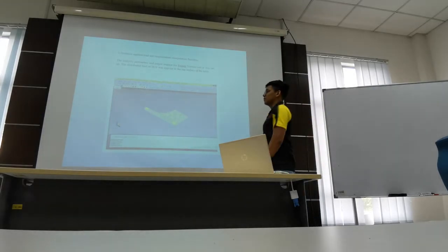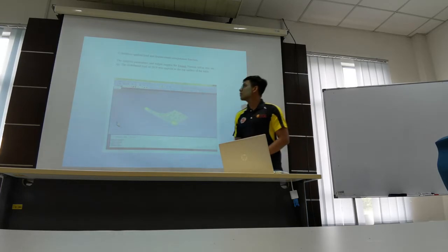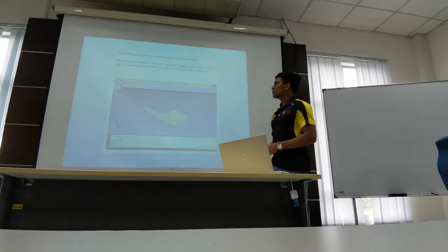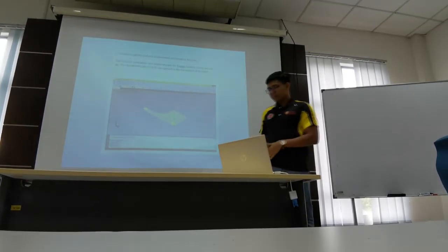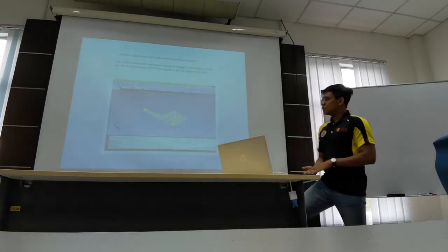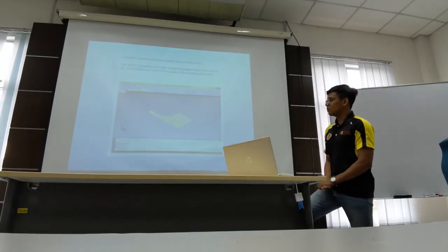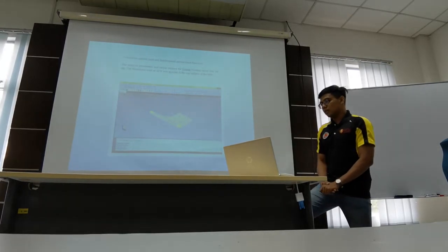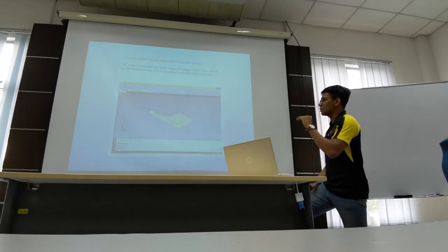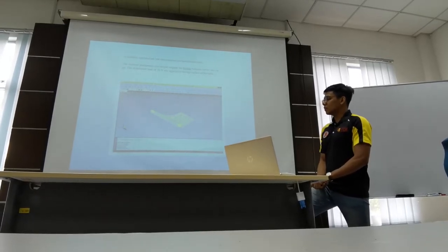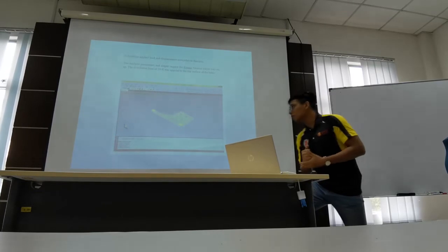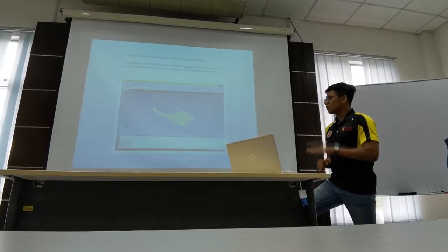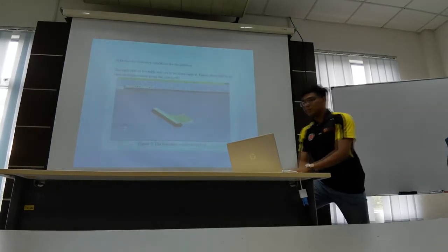So after we visualize, we mesh the object, we put a specific load, and we determine the displacement of the material, of the object. The distributed load we choose for this condition is 20 Newton, as told earlier. We choose this condition because it's almost the exact force as a human hand that puts on the table, and it's on the top of the surface of the table.